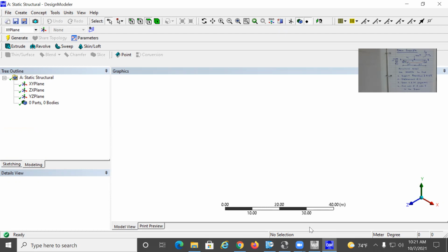All right. So now we are looking at this simply supported beam with support at the left side, support at the right side, and a load at the center. Of course, I can create the beam using 2 points, but then I'm not going to have a point at the center to apply the load. So I have to work with the end in mind.